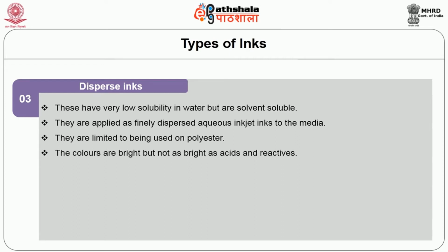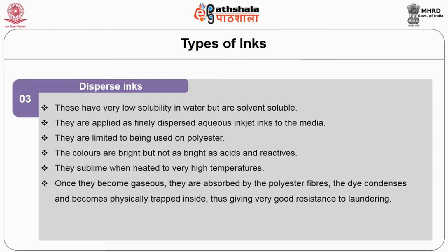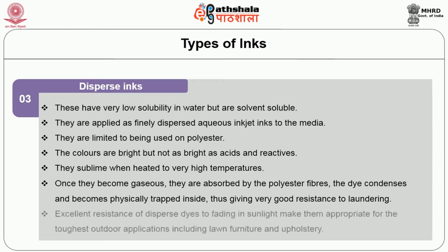The colors are bright but not as bright as acids and reactives. They sublime when heated to very high temperature. Once they become gaseous, they are absorbed by the polyester fibers. The dye condenses and becomes physically trapped inside, thus giving very good resistance to laundering. Excellent resistance of dispersed dyes to fading in sunlight makes them appropriate for the toughest outdoor applications, including lawn furniture